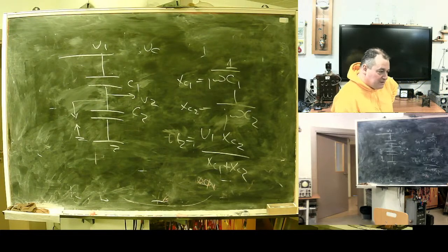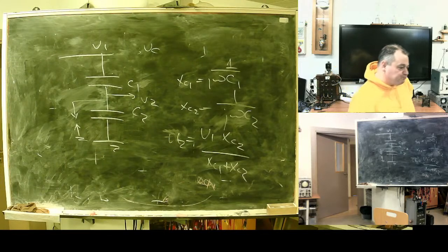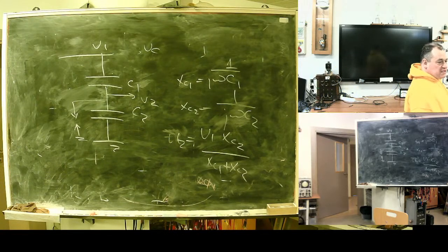You think, can a DC transformer exist? It's nonsense, it's against physics. But they do exist: current transformers for DC lines. The idea uses saturation.